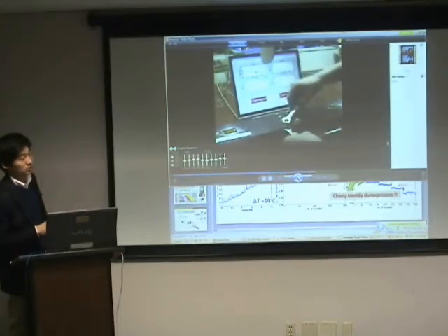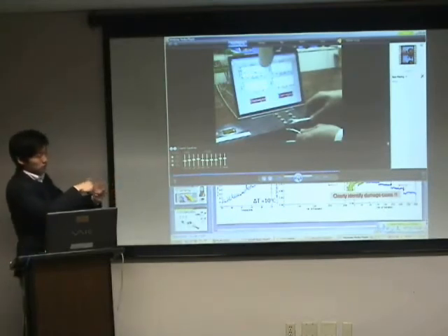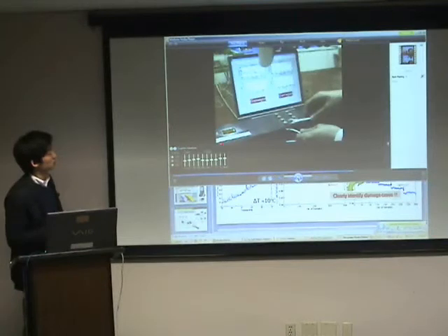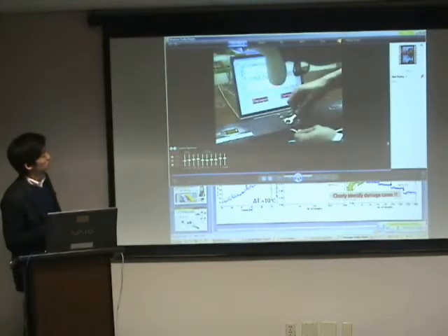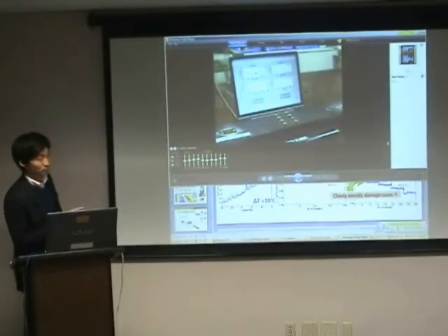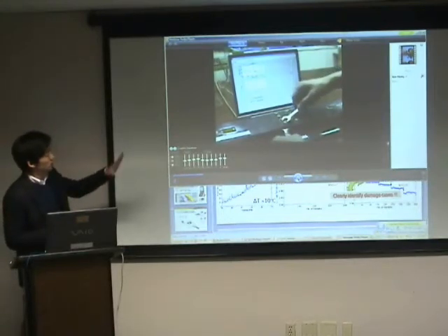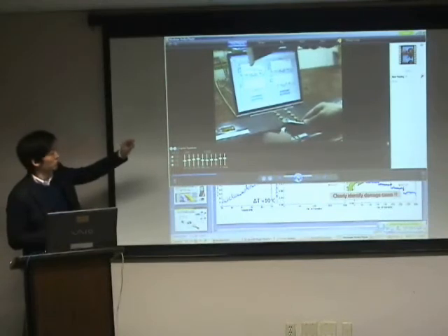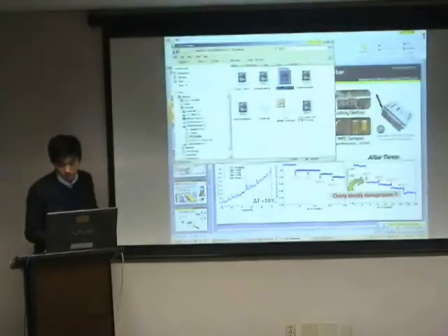then the damaged condition. This is real-time alarming. Then I again retightened the bolt to the original state. Then the PZT sensor integrated structure. Then we can see the normal condition. Yeah, it should be the normal condition. Yeah, you see? Okay. Anyhow, we can monitor the loosened bolt condition of the joint member by using this technique in real time.